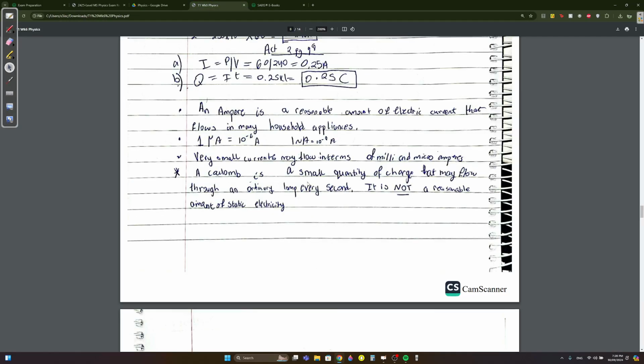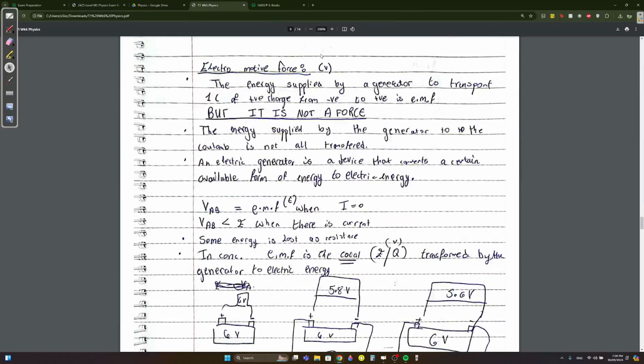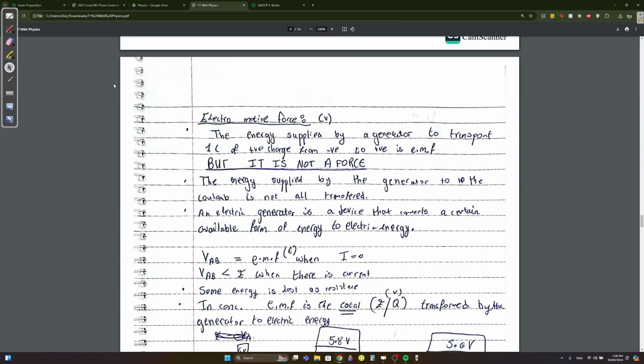Yeah, that's it. Go back to the notes. Okay, now the EMF, electromotive force. This is very important. I'm gonna help you understand it. We call it electromotive force, but it's important to know it's not a force. Okay, look, a battery, positive, negative. You connect it to a circuit. I get the voltmeter here. The voltmeter on the battery gives me 15 volts. The voltmeter then gives me 14.78 volts. You can say, what happened to the other 0.22 volts? I'm gonna tell you they got lost.